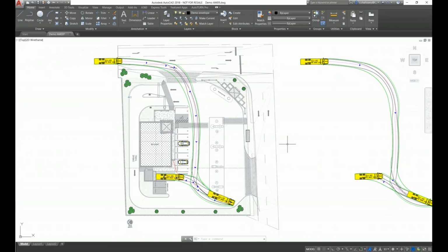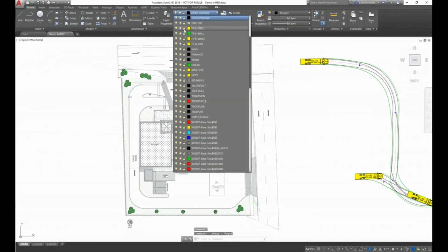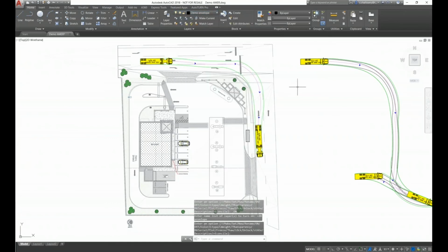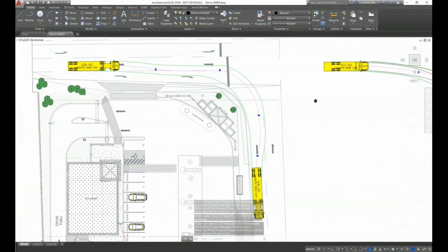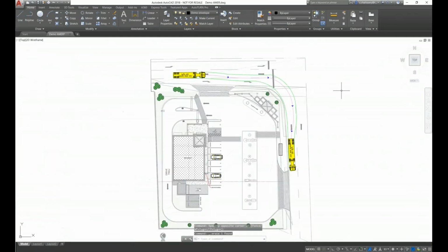So considering all these factors, it's easier to identify how the simulation was created in the software, and it can be reviewed. Well, let's consider one more scenario to wind up today's demonstration. So you have been given this simulation, which is for a WB40 from the AASHTO 2018 library. And how do you check if this simulation is good, or how do you review this simulation is perfect?